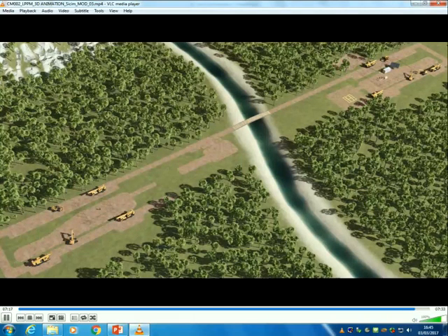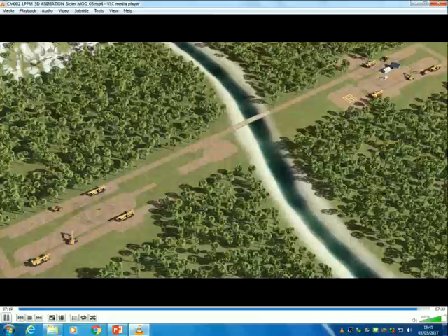So that was it. So hopefully that gives you, that's a real life project. It's a very big project, but it gives you an indication of what hot tap and stopple is. Okay, so any questions? With a bypass with a large volume, would you have to control the filling rate of that to avoid slugging in the main pipeline? Yes, you would have to.